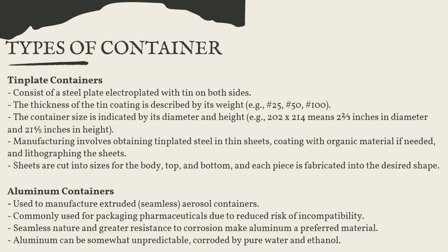Aluminum containers are used for manufacture of extruded seamless aerosol containers, commonly used for packaging pharmaceuticals due to the reduced risk of incompatibility. Seamless nature and greater resistance to corrosion make aluminum a preferred material. Aluminum can be somewhat unpredictable, corroded by pure water and ethanol.